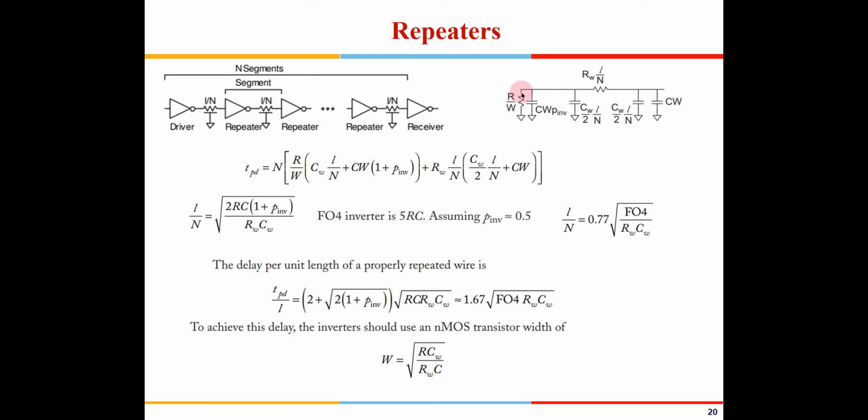So this resistance is going to see this capacitance and this capacitance in parallel, so they get added up, and in the next stage we say this plus this into this. That is why this particular resistance is taken out in common, and all the capacitance as seen by this resistance is written out here.